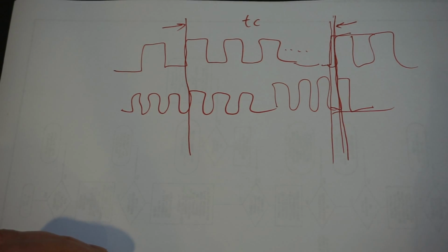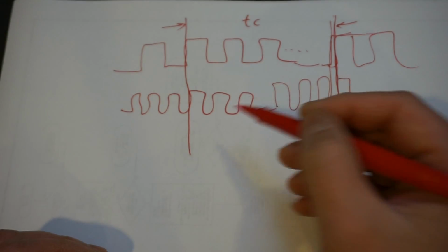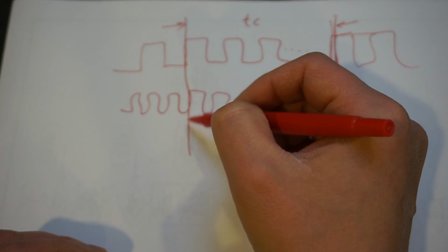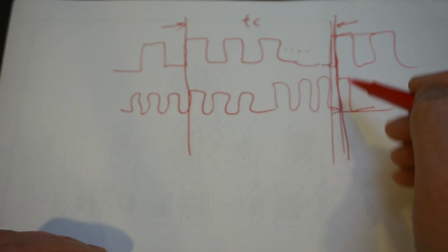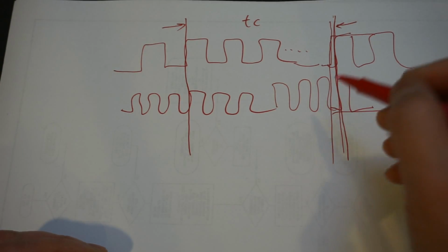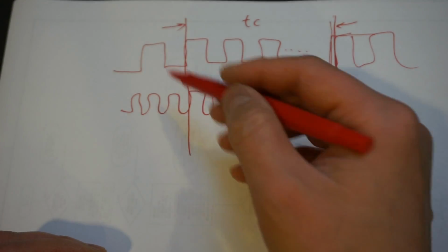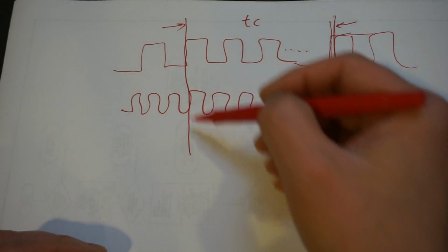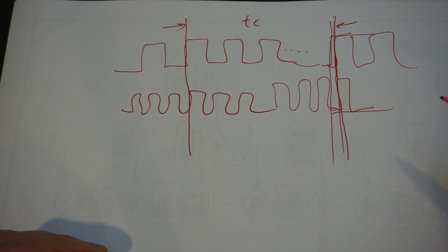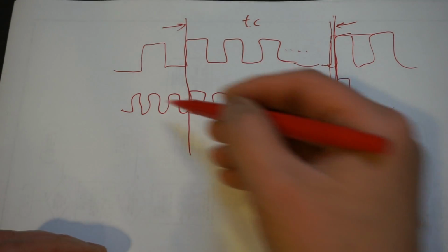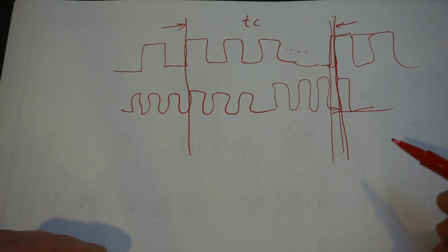Now, obviously, from this way you can see that because we're aligning up the input pulses with the clock pulses, there's no error in my clock pulse counting because the clock pulse is no longer free running. It's actually latched on to your input signal. And so in this way we can totally get rid of the plus and minus 1 frequency error.